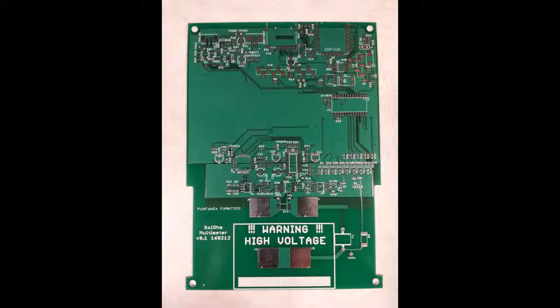It did have notches cut out of it. Part of their fast service was they said that they don't want only rectangular boards, but they notched this one. Right there in the high voltage section, there's two big squares, as well as right above there. Those are for the solder lugs, and they definitely did not want to put slots in there in the 2-day turn. That was extra cost as well. So I'm going to have to mount those solder lugs that do have a tab coming off of them somehow into these places. But I'll take care of that.